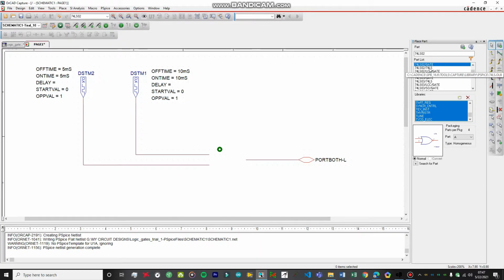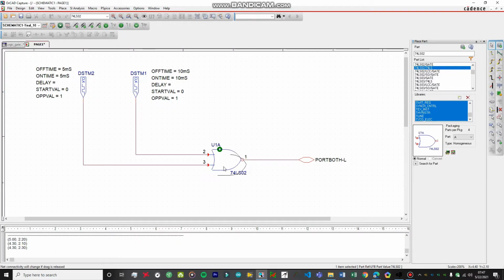It's just a design cache that we can use in our designs. This other IC has a simulation profile. You can see over here it's showing me the model. PSpice has a model available for this particular IC. Let's import it over here, remove this green warning, and then simulate the circuit again.